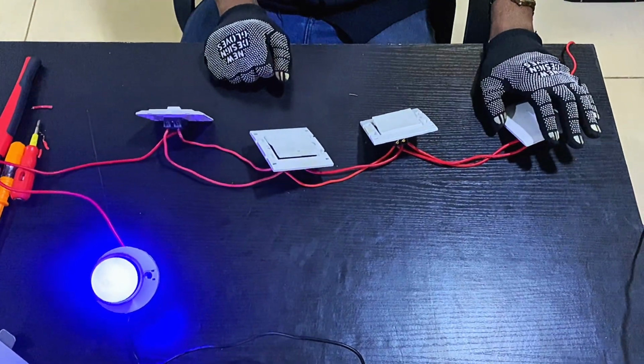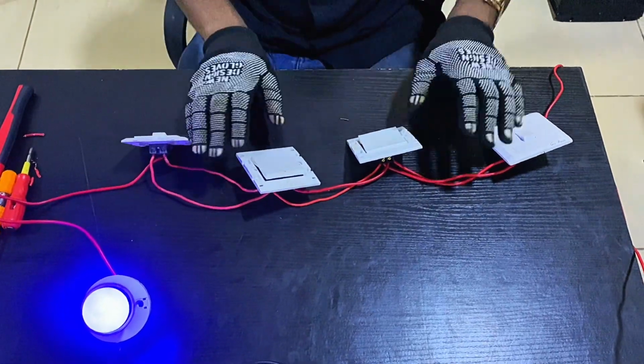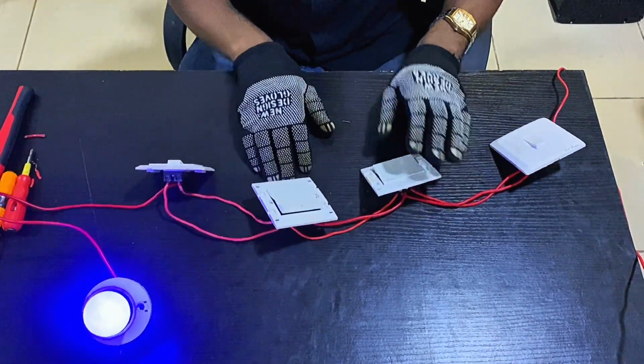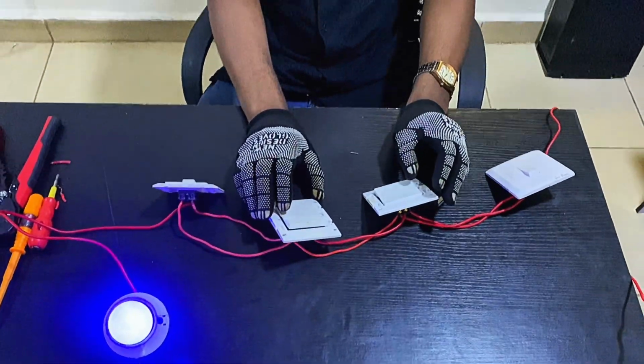So your first floor is your 1 gang 2-way switch. Your last floor is your 1 gang 2-way switch. Then in between, you have an intermediate switch. And take note, intermediate switches are usually very scarce in the market. In our next video, we are going to do a very comprehensive video on how you can use the 2 gang switch to actually connect an intermediate switch.